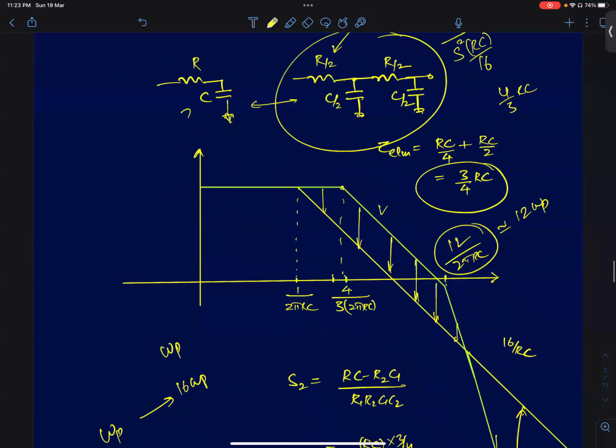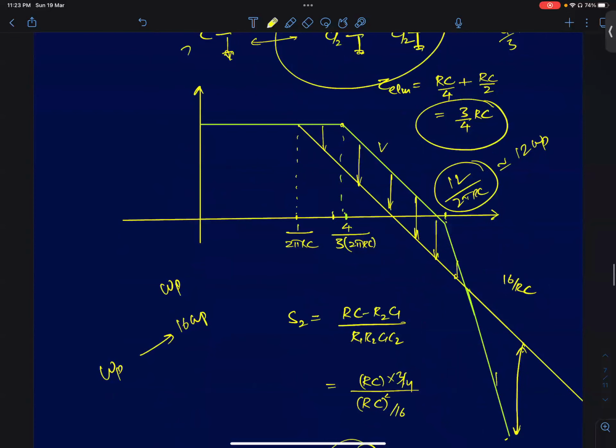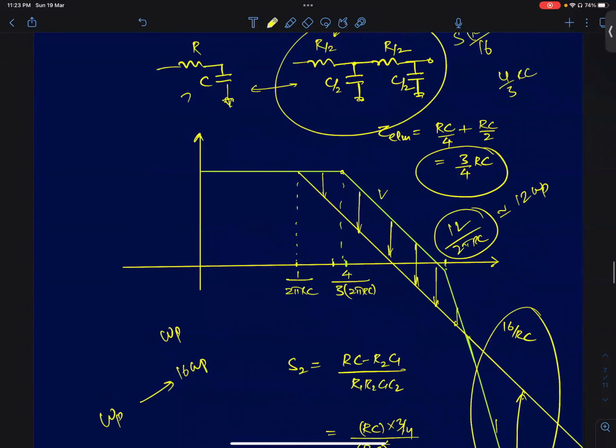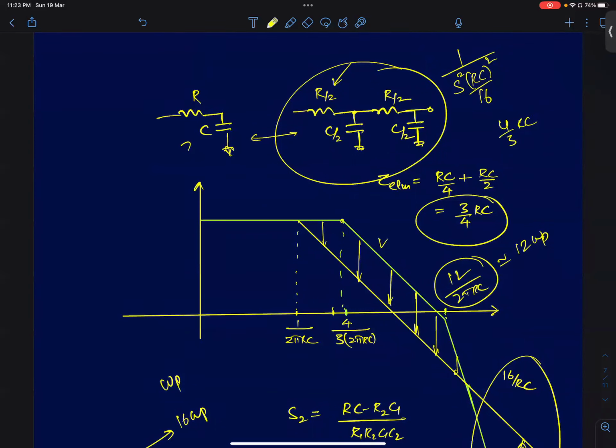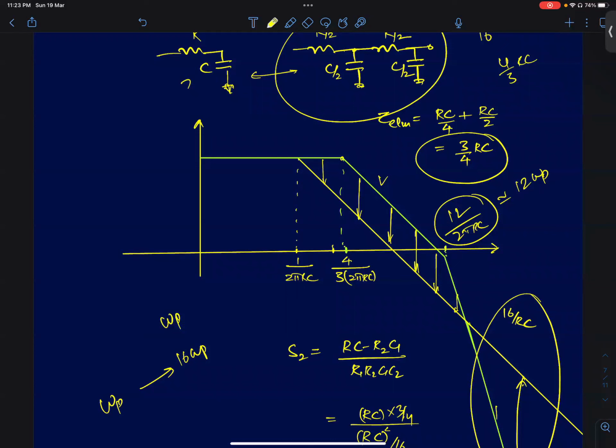Okay, and I was interested in canceling spurs in this region. So I went for a second order structure. So if you want to cancel out higher frequencies first, a second order RC structure is always going to be better than a simple RC structure. Okay. And how many RC cascades you need to add? That you can decide from simulations, whether you get better rejection or not at the frequencies of interest.